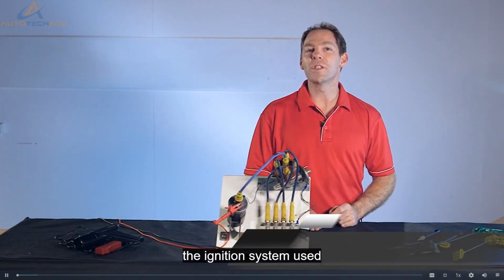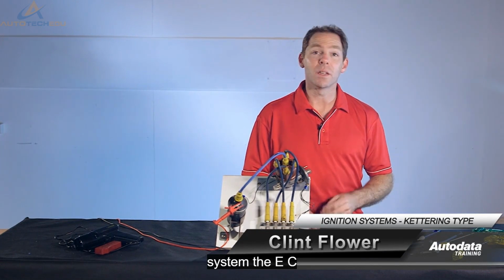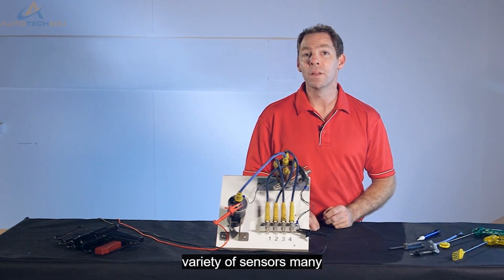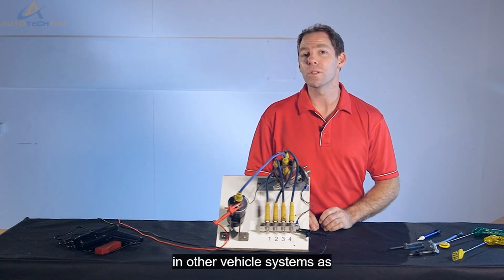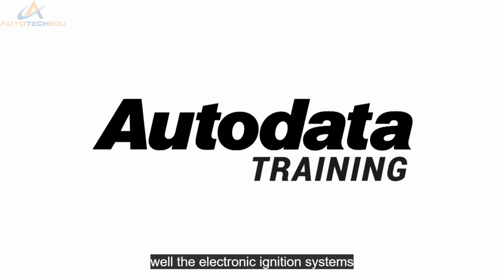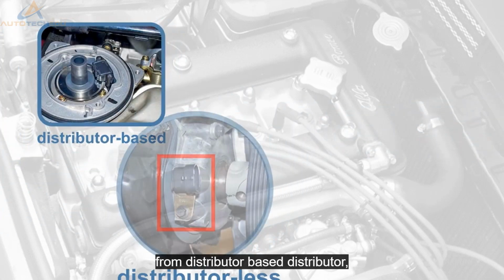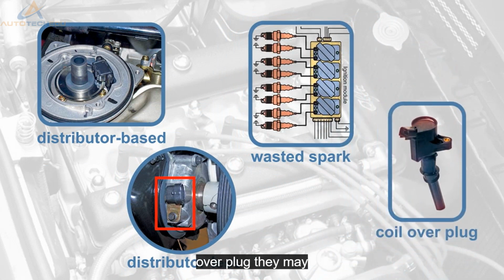The ignition system used in today's vehicles is only part of the engine management system. The ECM controls all the functions of the ignition system in response to inputs from a variety of sensors. Many of the inputs used in the ignition control are used in other vehicle systems as well. The electronic ignition systems currently available to manufacturers range from distributor-based, distributorless, wasted spark to coil overplug.